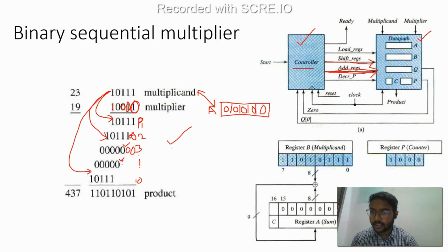What will you write, the rightmost bit? 0 0 0, because of your final product, let's call it c0, c1, c2. Your c0 is the sum of all the partial products at the 0th position, the LSB position. So you will have only this one and all others are 0. What is your first step?